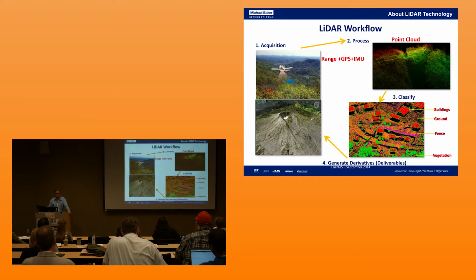Together, you bring all the 3 data sets together to create what we call a point cloud. A point cloud is nothing but a stream of points with the XYZ values, and that's what we are seeing on the second imagery. And the point cloud will have points or reflections that come from the ground, as well as non-ground features like trees, etc.